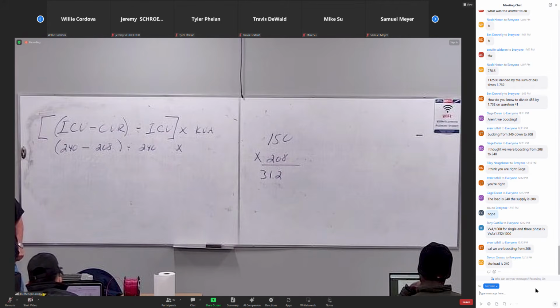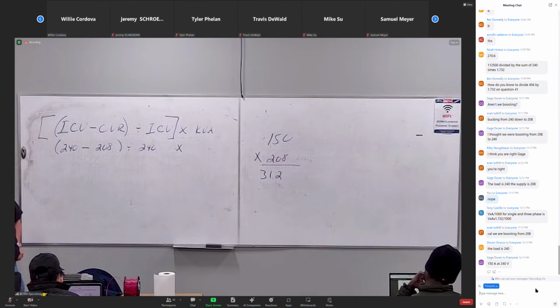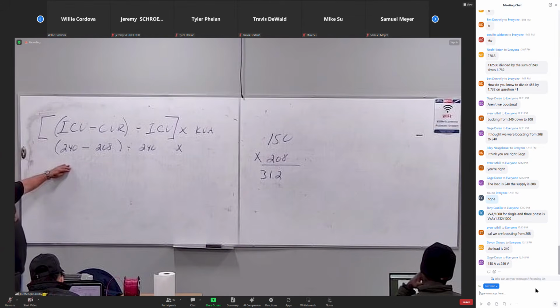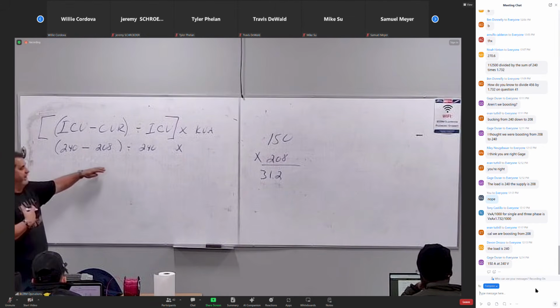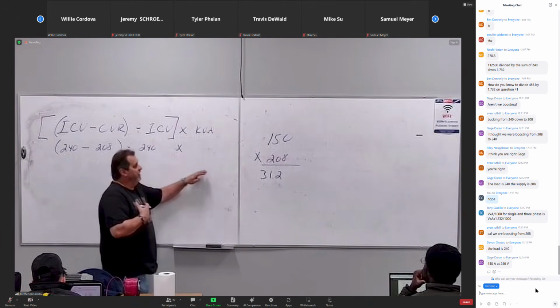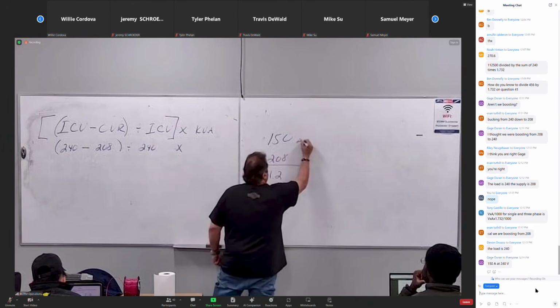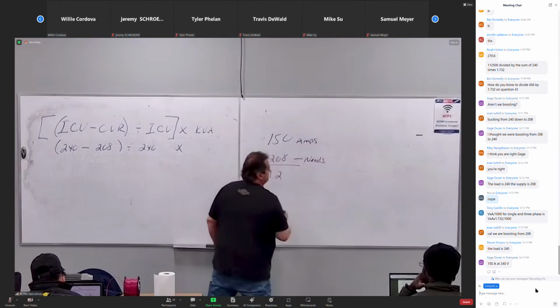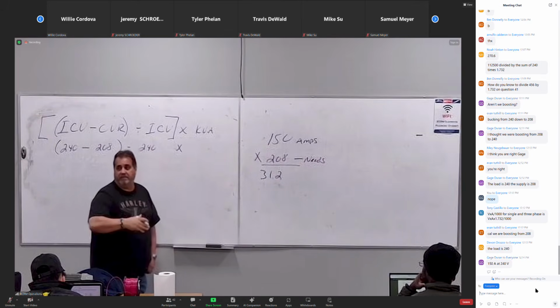Okay. So because we interpreted the question wrong, and I should have read it first, that's not what the question is asking. So forget about the question. Let's look at the scenario. Our scenario is different. We have 240 volts. We want 208. We're bucking. So in order to determine the KVA, we take what the load is rated at times the voltage that it needs. Does that make sense? Every single time.